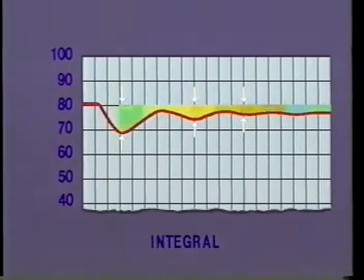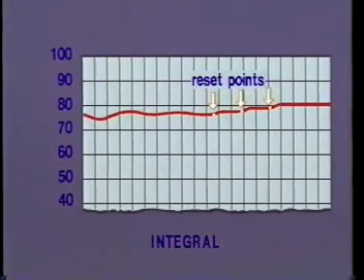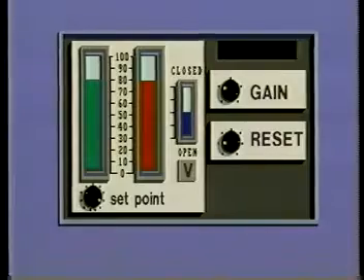In effect, it monitors the average error over a period of time. In this way, when the system experiences a load change, the integral unit will detect that the error, although constant, is still present after some time. It will then move the action of the proportional unit to correct the error or offset. Because of its ability to return a system to its set point, integral action is called reset action. In effect, the integral unit makes frequent checks on the performance of the proportional unit. If it finds there is an offset, it shifts or resets the proportional control action to eliminate the offset.